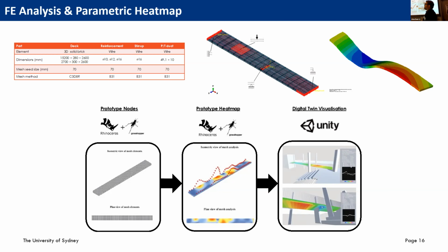I guess I need to correct this understanding that we are measuring corrosion. We are not measuring corrosion. We are measuring humidity, and that humidity gives us an understanding of how much seawater and chloride ions have penetrated into the structure.